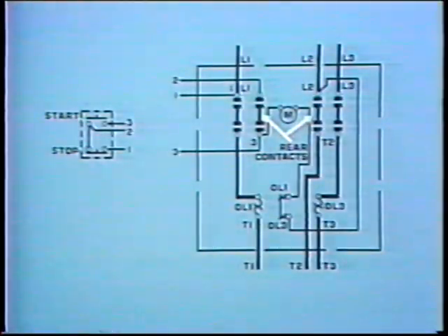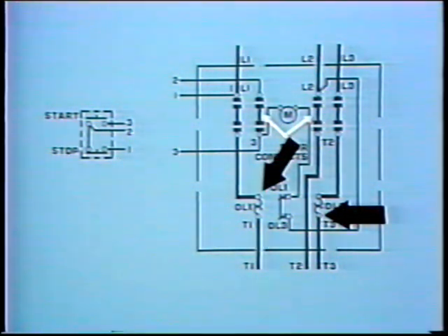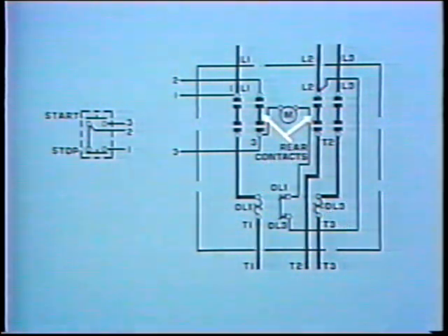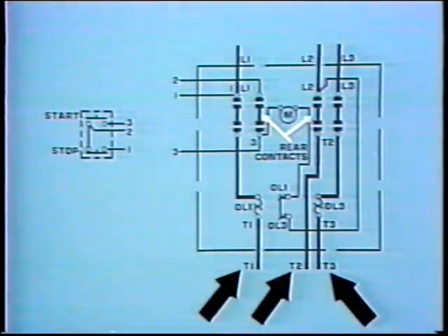Remember, the schematic does not show a physical representation of the controller. It shows an electrical representation, so it is not necessary for it to show 2 sets of contacts for each power lead. But the wiring diagram does. The motor circuit of the wiring diagram also shows the overload heater elements. In this particular wiring diagram, circles are used to represent points of electrical connection. Dots may also be used. The motor is not shown but its leads are. The motor leads are labeled T1, T2, and T3, the same as in the controller's schematic.